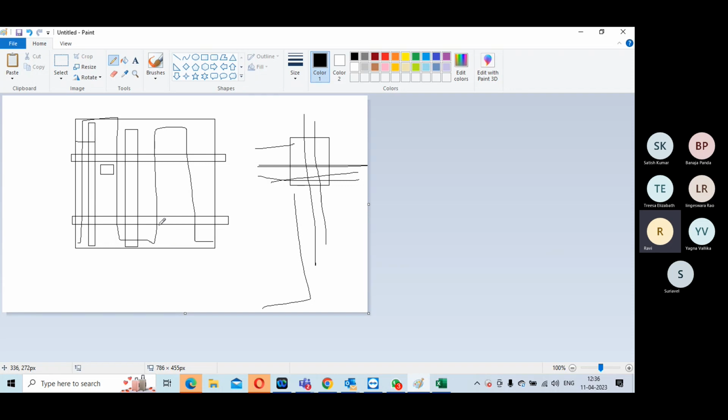So that the isolation always on wire will come in a single shot and connect. But this particular net which is connecting will be short, and you cannot have it long because the wiring has to be very short. So you'll have to place it in accordance with that. Isolation cells, four, four, four like this, you can line up, connect properly, and align properly in terms of floor plan, so that you are causing minimum disturbance.